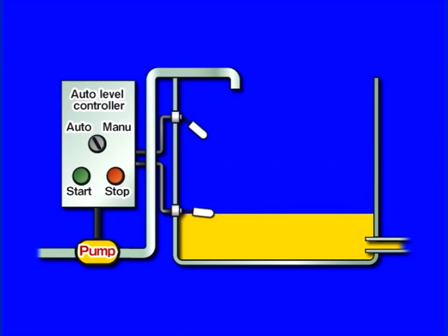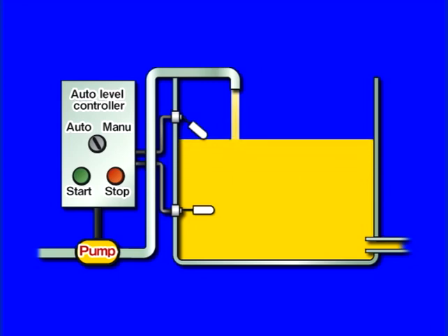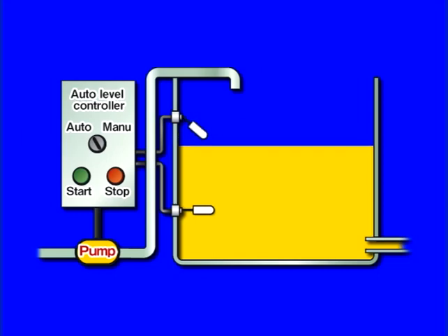To prevent such accidents, an electric space heater can be installed in the motor. The space heater is off when the motor is running, and it turns on after the motor has been idle for a preset period of time.